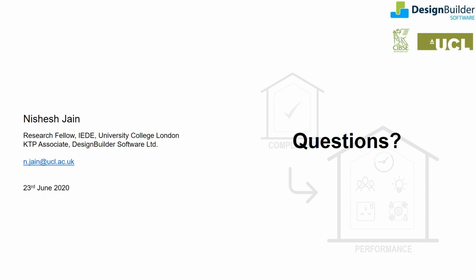Okay, so replacing some of the modeling with actual data. Yeah, it links to the calibration question, which I think is the first or second one. There are two different approaches to modeling. One is building physics based modeling, which does calculations for building physics. It looks at all the heat flows and thermodynamic transfers, which is effectively what EnergyPlus and DesignBuilder do. Another line of modeling is more mathematical modeling of results, creating artificial intelligence sort of models, which look at trends from large sample data and help you identify patterns, but they work at stock levels.